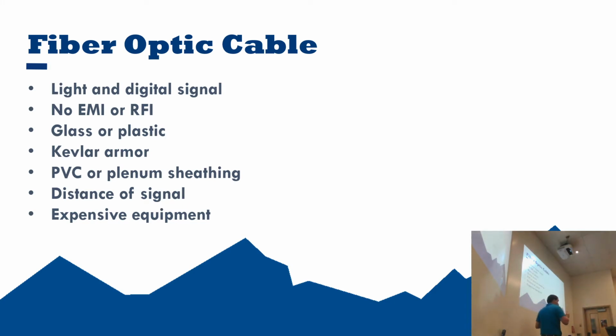All right, and because it's not using any sort of analog signal, or any sort of electricity to conduct a signal at all, it's not subject to EMI or RFI. So of course, we're talking about electromagnetic interference or radio frequency interference. So that's a very beneficial thing, because if we're running them through a ceiling or next to a lot of other cables, you don't have to worry at all about any sort of interference.